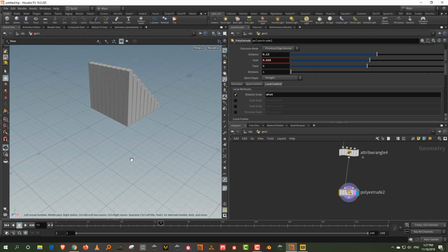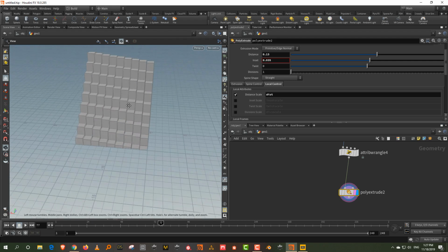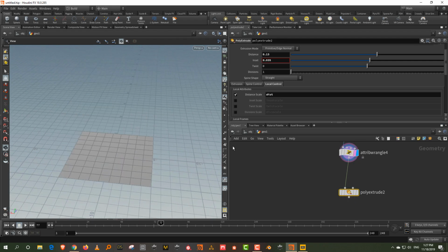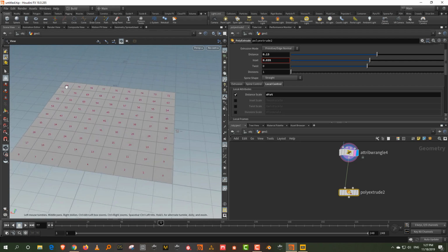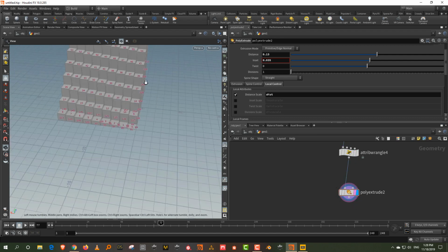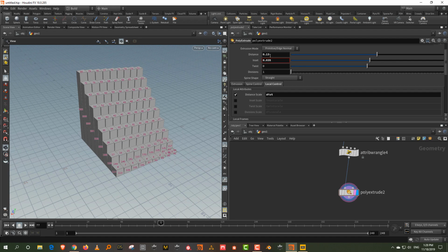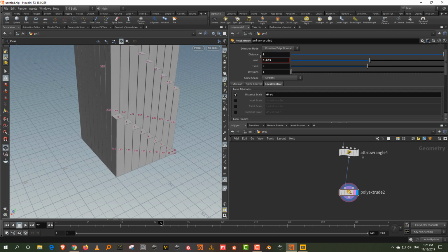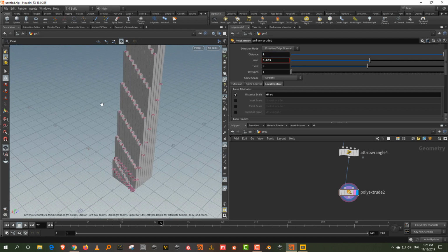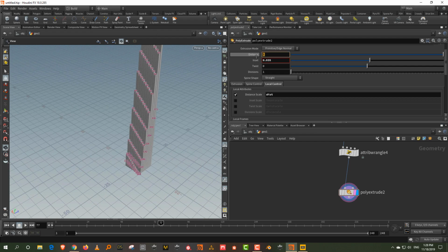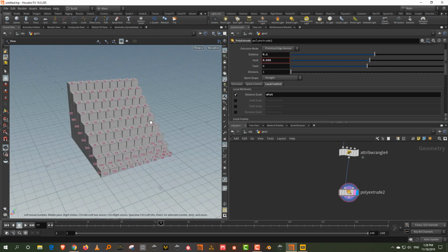And see, what you've gotten is each face is extruding to the amount of its primitive number. So if you come down here, see, 80 is going all the way to 80 and then 0 is sticking to 0. But what it does is that it actually multiplies it with the distance value. So if the distance value is 1, then it's going all the way to 80. Okay, but if the distance value says 0.1, then it's only going to like 8.